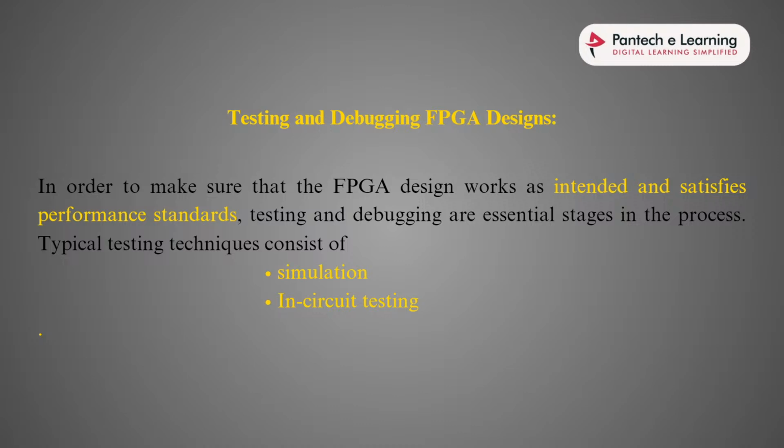Why? Because hardware often makes mistakes, the tools also make mistakes, and there may be a mistake in our RTL code also. For those reasons, the output frequency may come out wrong. So we have to test the FPGA and debug if an error happens, if we do not get the required outputs. We have to debug the FPGA design, like the RTL and logic synthesis. We have to change the required design in the process of testing and debugging FPGA designs.